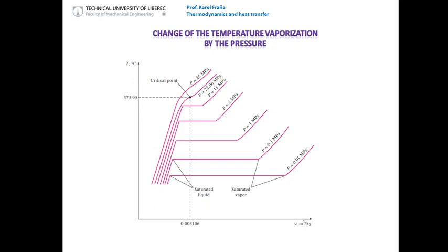If you are above the critical point, this change between the gas and liquid can happen chaotically, and it's not practically possible to apply in engines. So all engines, all cycles practically, which we can imagine, the heat cycles, will be working with a pressure definitely lower than 22.06 megapascal. Even 50 megapascal is too much.